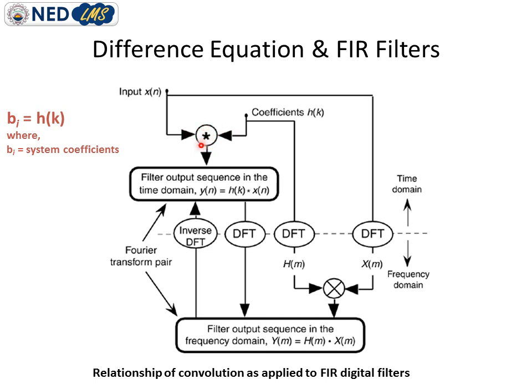Here the asterisk sign represents the convolution process. Please remember that the asterisk is always used to represent the convolution process. Now after convolving the two inputs, the first being the input signal and the second the coefficients of the impulse response, we will get the filter output sequence in the time domain. This is important, as we are convolving two sequences which are in the time domain, because the impulse response is in the time domain and the input is also in the time domain, represented by x of n.